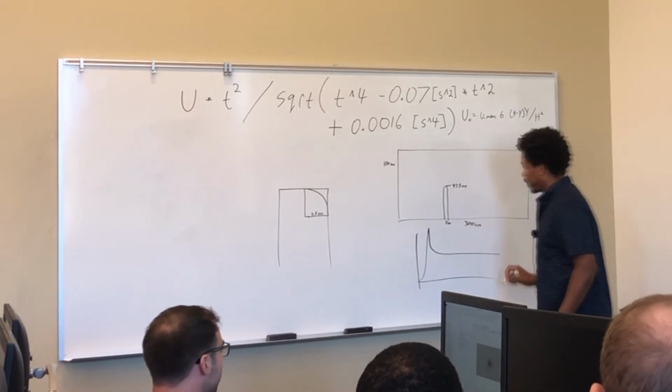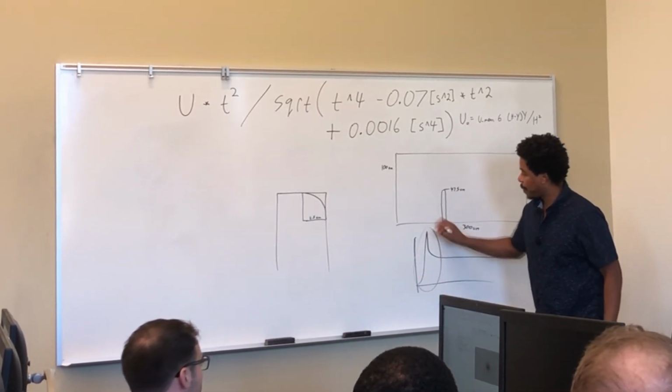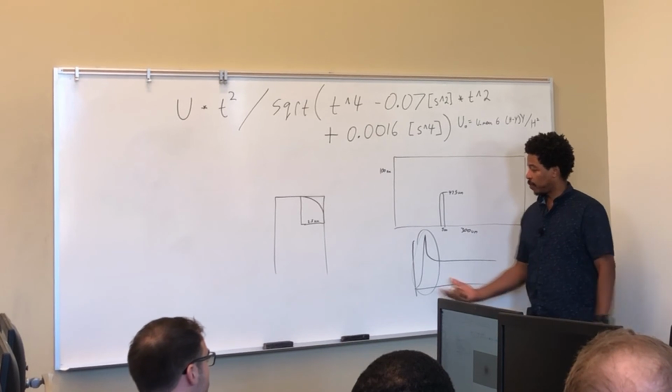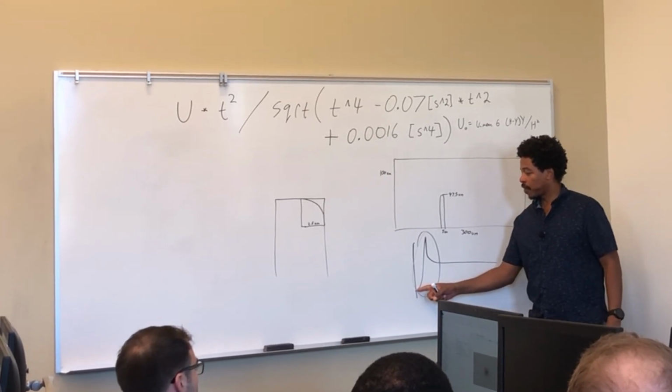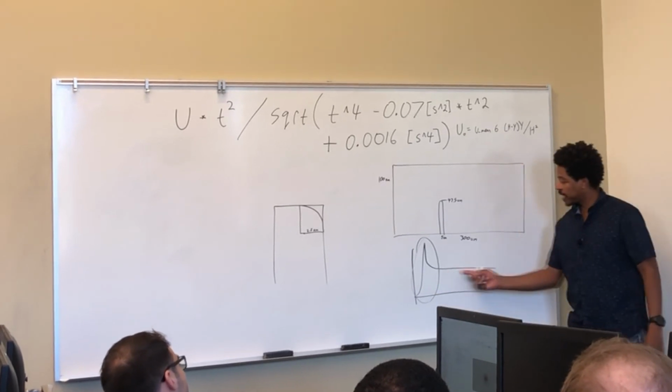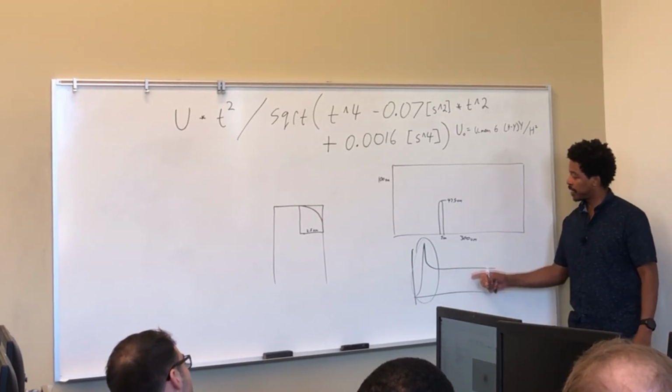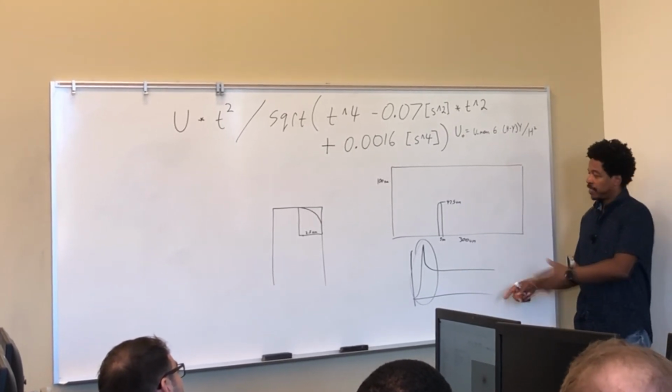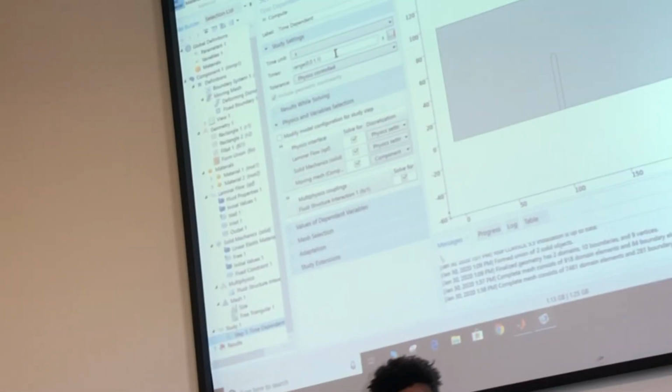A lot of transient is happening right there. So when we compute our solution, we want to be very careful as we step through here. After a steady state, not much is happening, so we could jump in time huge amounts. We're going to do that with range.